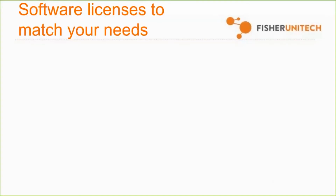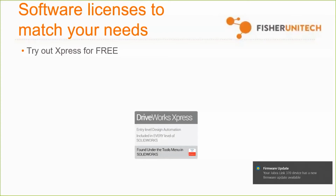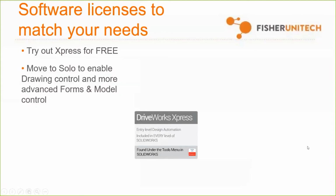Now, you've got 3 different software packages. You could either get DriveWorks Express for free, like we've talked about, where you can do some entry-level design automation. That's going to be in every level of SOLIDWORKS. Or maybe you might want to step up to Solo. That'll let you control your drawings, being able to put custom notes in there, being able to drive dimensions and things of that nature. You also might want more advanced form control so that things look a lot prettier, so complex combo boxes and picture controls and things of that nature. You're also going to get more complex model control as well.